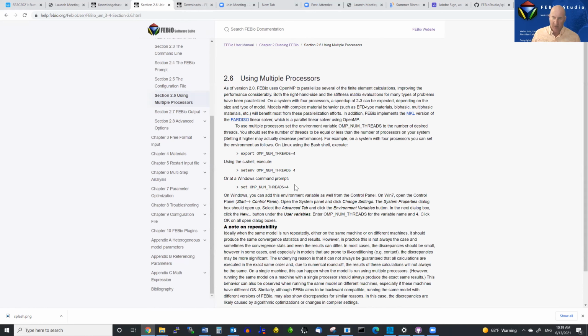At this point, it's worth discussing briefly the difference between a direct and an iterative linear solver. There are a couple of major differences. First, the direct solver is the most accurate, and it's always the more robust. In fact, it's safe to say that less than 5 or 10% of the types of problems people run with FEBio can be effectively solved with an iterative solver.